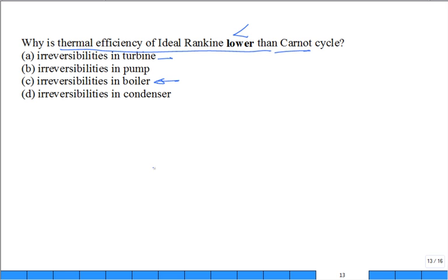There are 4 sources of irreversibilities that you're exposed to in Thermo 1: friction, unrestrained expansion through a pressure change, heat transfer through a finite temperature difference, that's the key here, and mixing. Go back and look at the discussion of irreversibilities in chapter 5. Kind of memorize those, recite them. And the one here for what's happening in the boiler is the delta T.